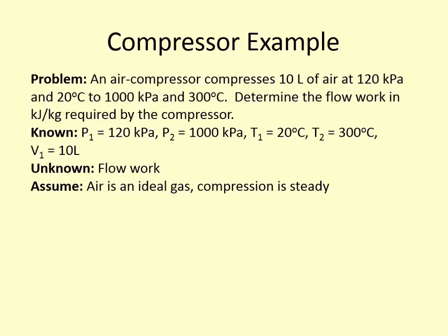So we don't know the flow work, but we do know initial and final states, and we know the total volume of air that we are going to compress. So we can make the same assumption that air is an ideal gas, and that our compression process is a steady process, meaning we're not oscillating and compressing it in a non-steady fashion.